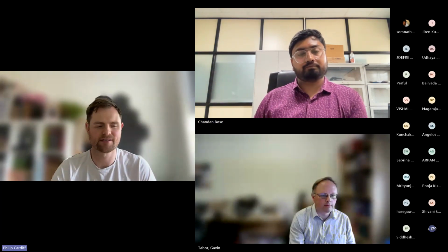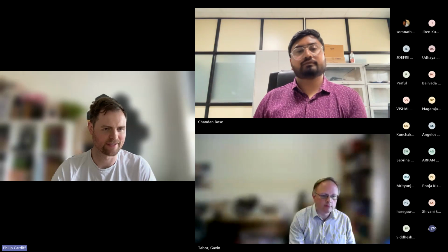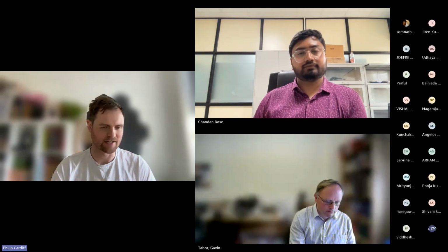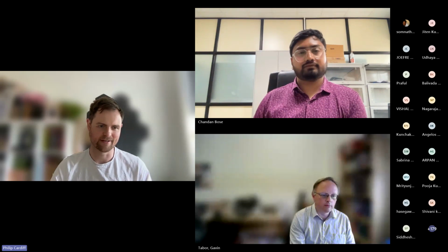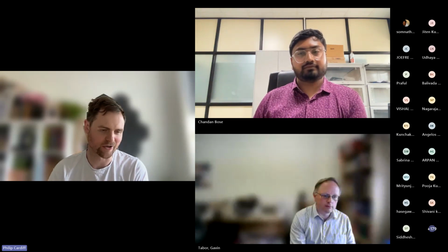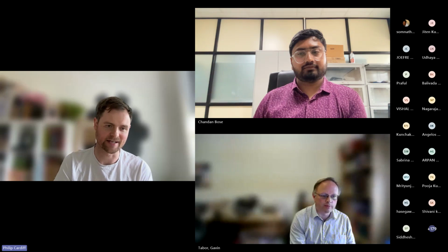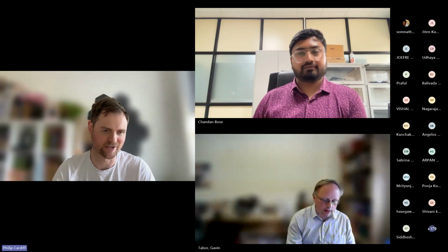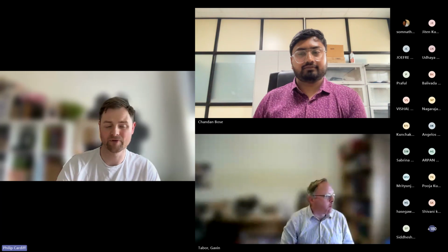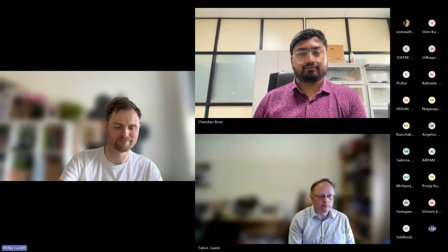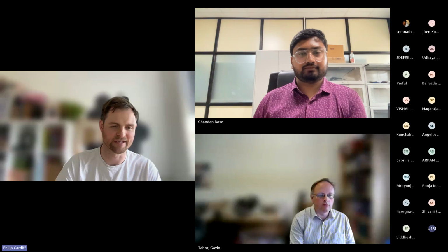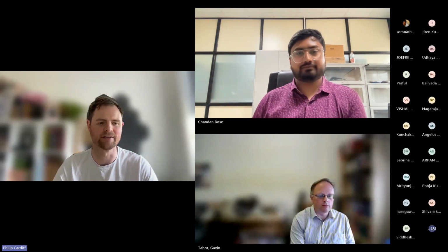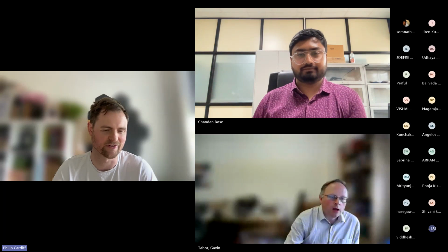So the way it's parallelized at the moment is probably not a very good way. So if you decompose the fluid and decompose the solid, say into 50 cores, then core number 0 has one part of the solid interface and has a different part of the fluid interface, and they may not overlap. So a naive solution is at each point before we do the mapping, we sync an entire copy of the faces and points at the interface, do the mapping, and then take the part you need. So that's probably okay up to like 50 or 100 cores, but